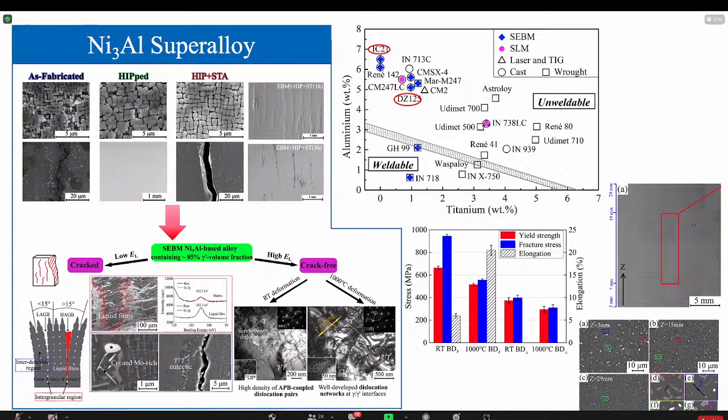Okay, well, I have a quick question, if I may. I'm not an expert when it comes to nickel superalloys, but my understanding is that the formation of the gamma prime precipitates and the control of that with post heat treatment is always critical. And I know you mentioned that the heat treatment was when the cracks formed. I just wanted to know, is that because of the formation of precipitates and the columnar structure that forms during the SLM process?